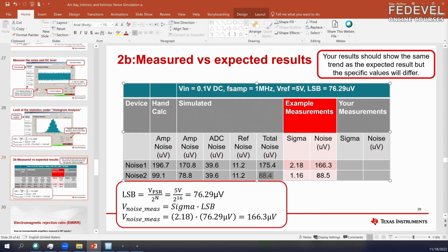So you really can see that you might get a little bit of error, 175 versus 166. But if you're really modeling everything correctly, they should be essentially equal. Of course, all components have tolerance: the amplifier, the resistors, and so forth. The capacitors used in the filter are going to have tolerance. It's going to change the filter cutoff, and that's why you'll see some variation.